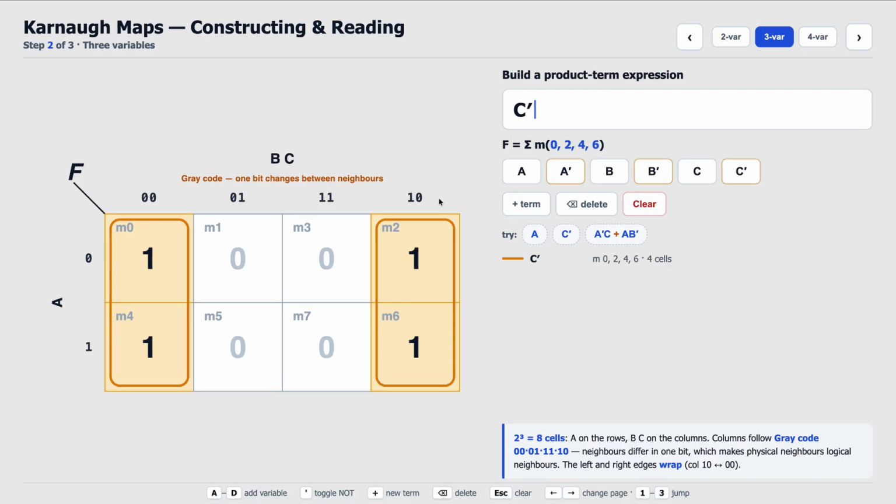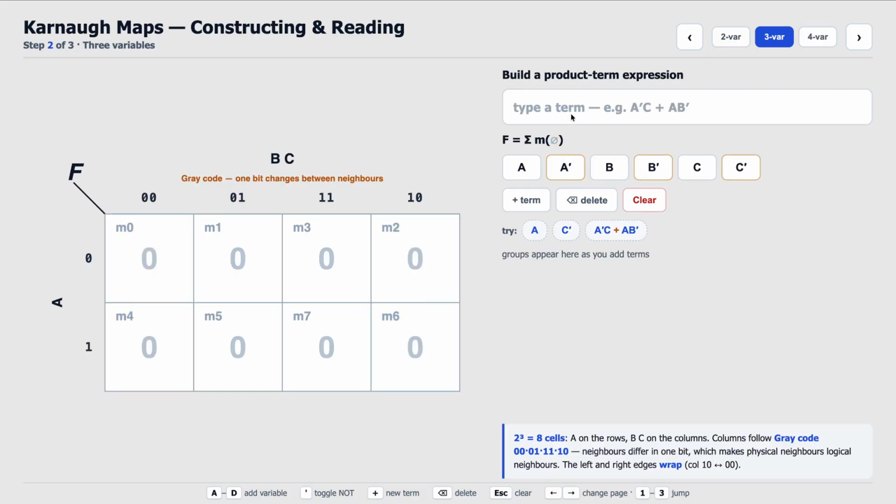All right. If I flip this order, the intersections don't line up right. And so the Karnaugh map doesn't give us the kind of representation that's useful. So it's useful to have only one bit change at a time as we move from square to square in a Karnaugh map. All right. So for example, when I move from minterm 0 square to minterm 1, all right, only one bit would change. All right. So that's the basics of a Karnaugh map.